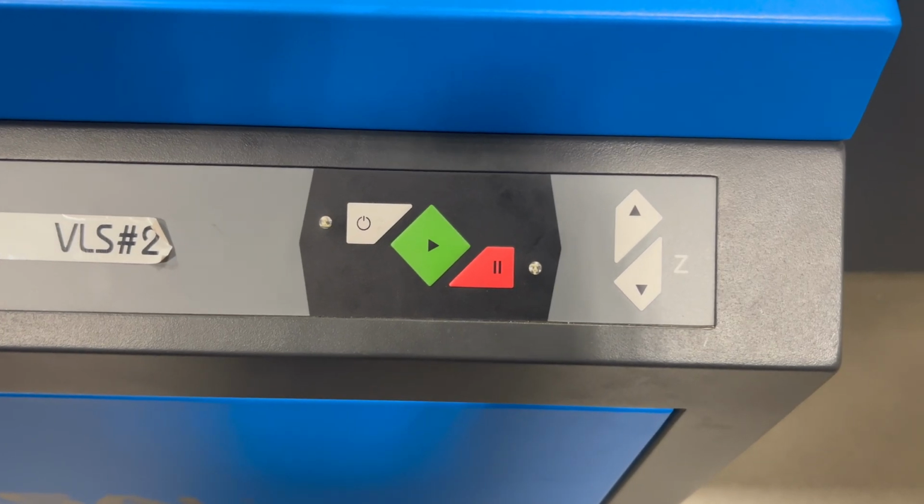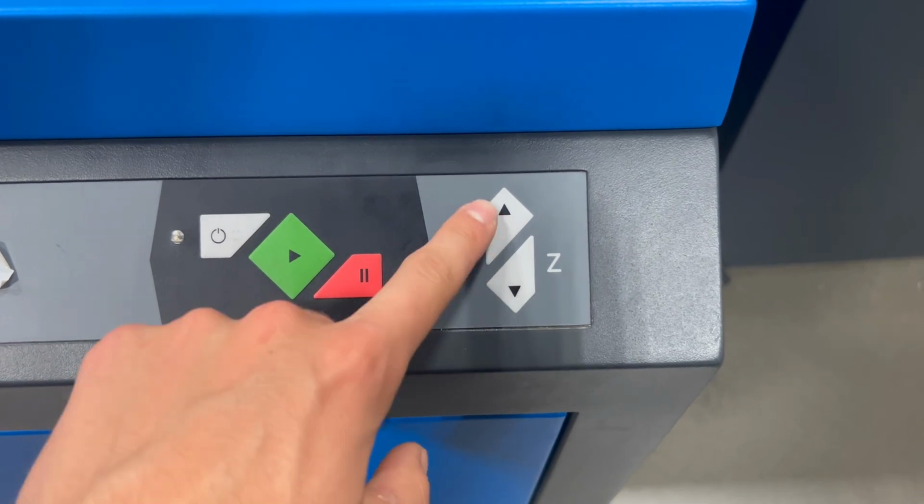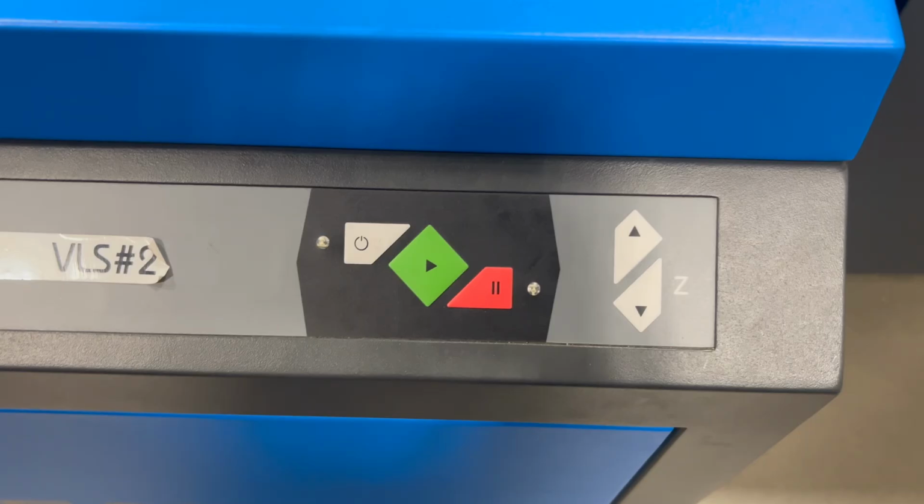Next, what we do is use the laser head move tool to move the laser head to roughly the center of our part. Then we use the included leveling tool and the Z-axis arrow buttons to make sure the laser is set at the right height above the material.